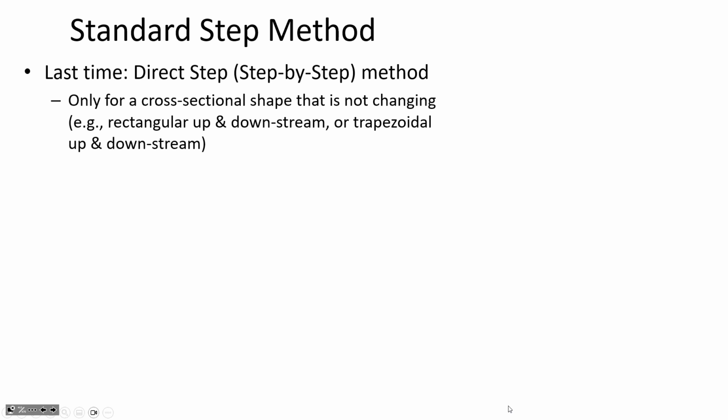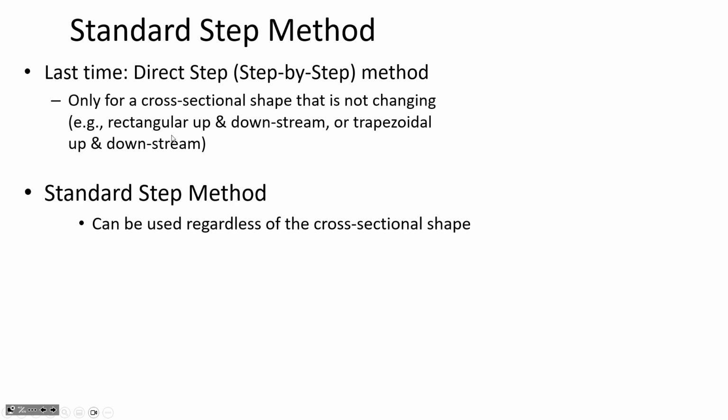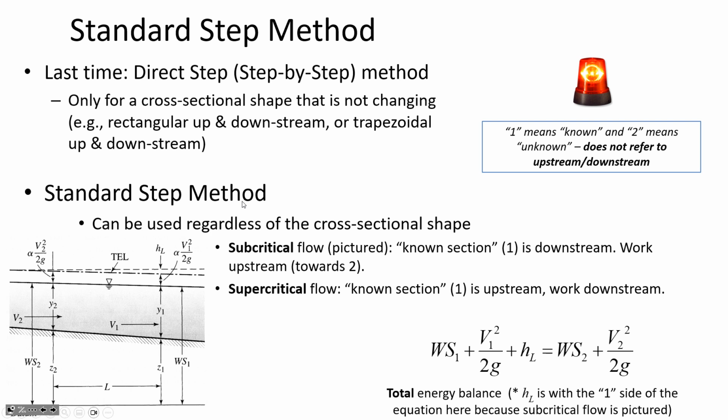So the standard step method is the solution to that. Last time, when we were doing the direct step method, we were only applying it really for trapezoidal or rectangular channels. But the standard step method can be used regardless of the shape of the cross section.